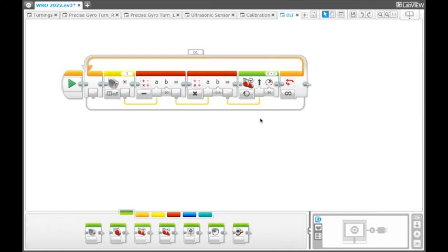If the line is taking a turn, the robot has to also move along with the line. So if it is having a sharp turn or a different type of curve, then it is turning based on the value you have given here. If you don't have a sharp turn, then you can reduce this value. If you have more sharp turns, you can increase or decrease the value for this. So you have to fix this value.